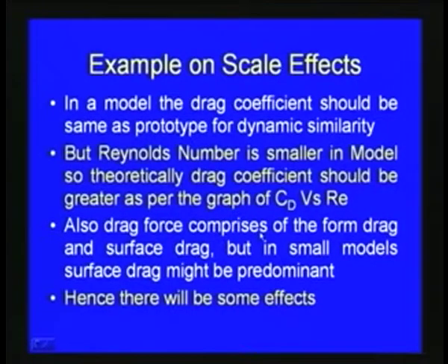Also, the drag force comprises the form drag and surface drag, but in many cases in small models surface drag might be predominant, and the form drag may not be predominant. So, we can see that there will be a lot of scale effect. These are the problems while doing, typically, the drag effects for particular problems.